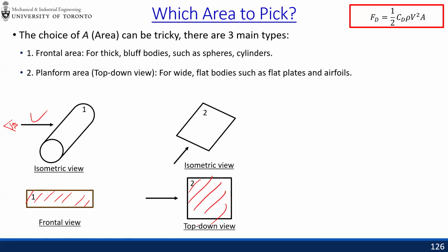Now, there is a bit of a trap when it comes to calculating drag force for a plate. If the plate is in the middle, and this is your velocity, you have to multiply the drag force afterwards because you're going to have flow on both sides. And quite often, even when I was doing some practice a couple of days ago, I forgot to multiply it for one of the questions I was practicing on.